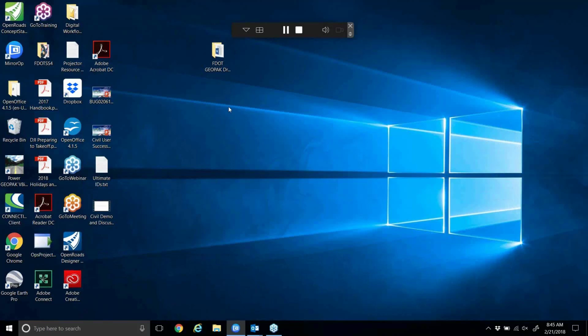If you flip over to 1.4, since this is our design class, we have this general design process for the storm drains. And you can see here it's steps 1 through 11. We're going to do just about all of this. We're going to have a new project file here in step 1. We're going to pick our inlet locations. We're going to define area to each node in step 3. We're going to link the inlets together with pipe segments. We'll create a network from those nodes and pipes here in step number 5.